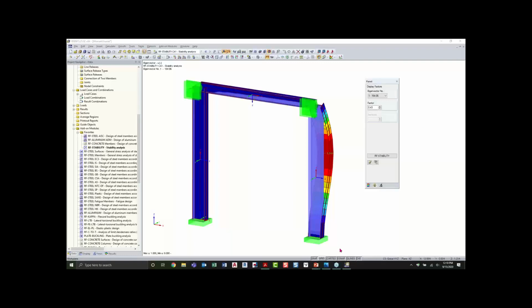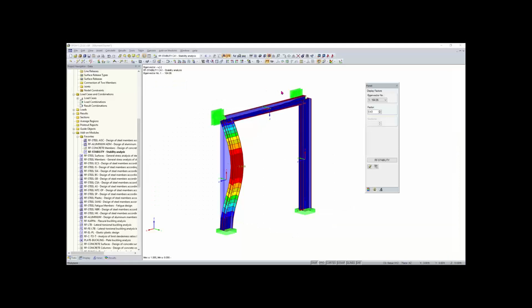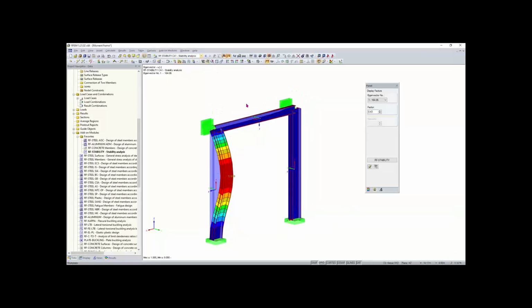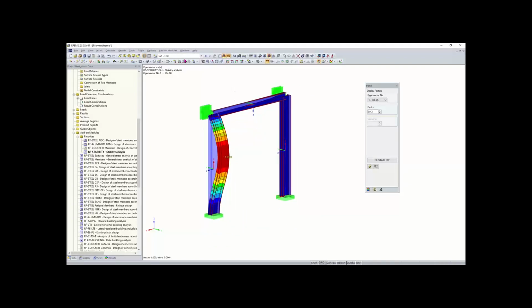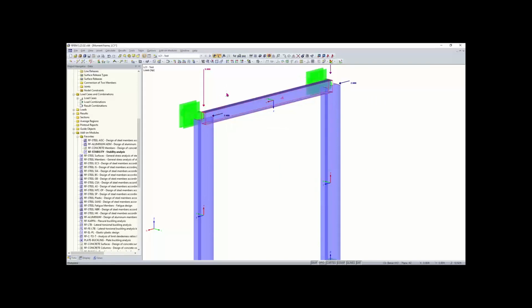I'll just pull up. So we have a quick question just saying, how do we add lateral loads? And I do believe in your last example, you had applied a lateral load to your column. Do you just want me to go over how to apply those? Yeah, I think I'll just explain to the user quickly that the lateral loads can be applied the same way as gravity loads. So Alex has been applying loads in the global X, Y, and Z directions. So lateral loads would be in the X or Y directions. You can see here 2 kips, for example, is in the lateral direction. So that should answer the question.